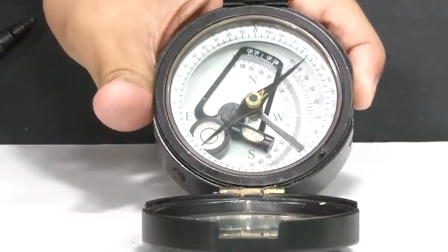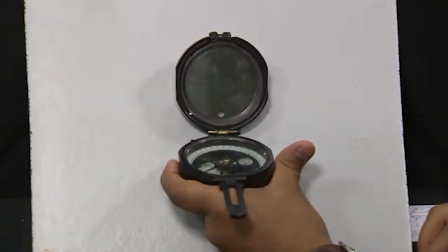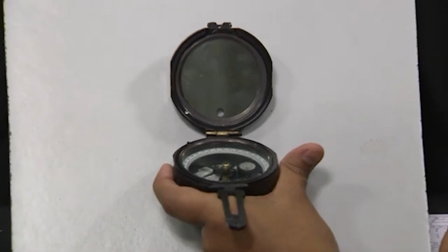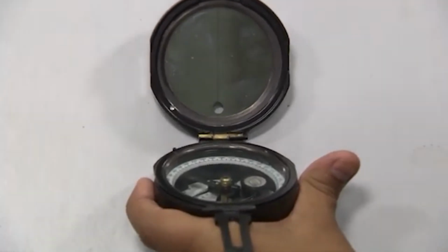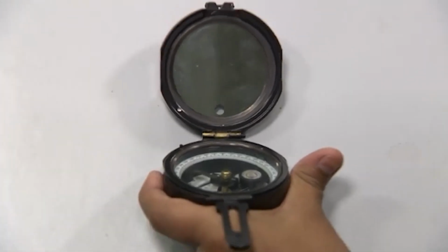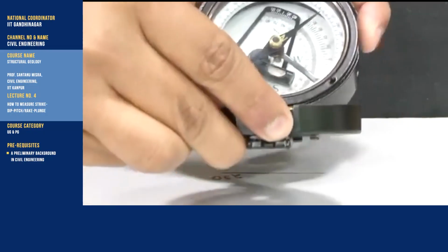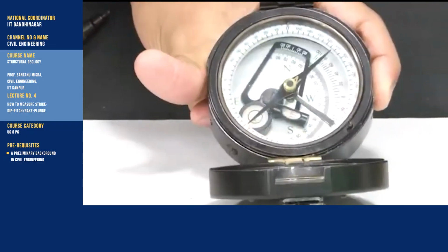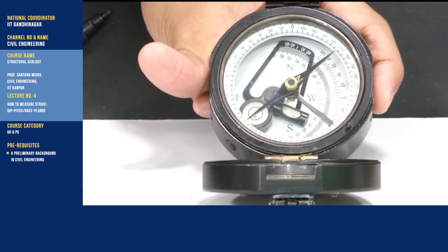So now we put this edge to measure the dip direction against this plane, and in the strike line the edge is placed against the strike line, and now we will measure the dip direction. As we know from right hand rule, the dip direction would be 220 plus 90, so 310 degrees, but we still would confirm it. So in order to confirm it, the compass position is this, and now we will make it horizontal. Once we have achieved the horizontal position in the compass, we would take the note of the northern end of the magnetic needle.